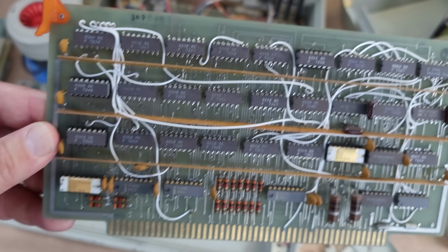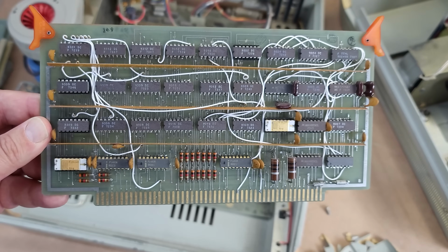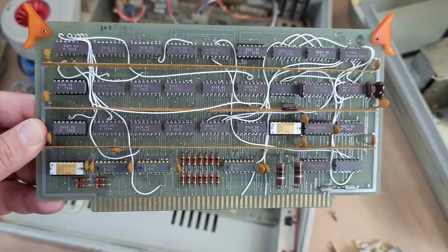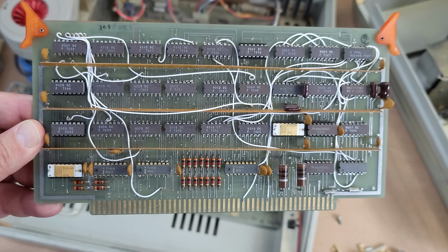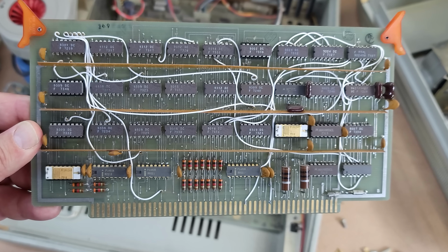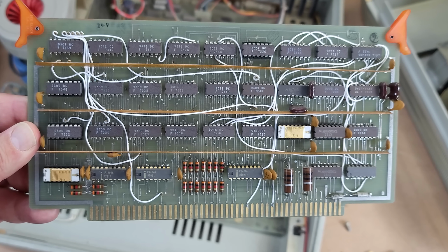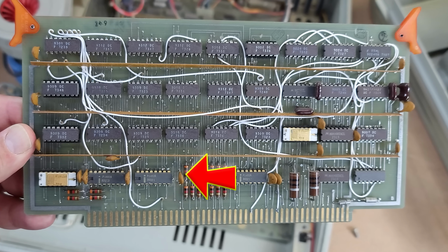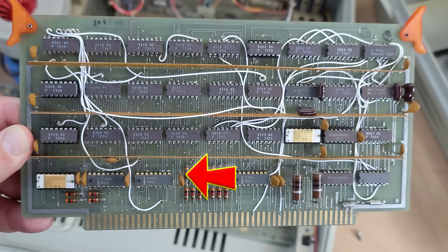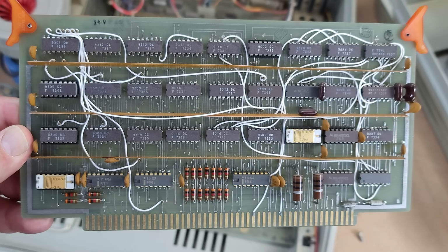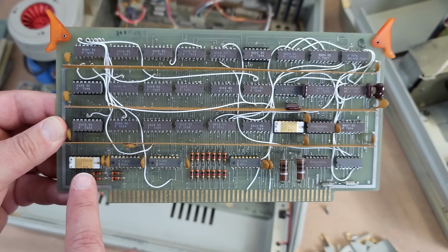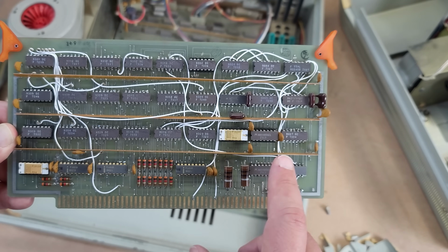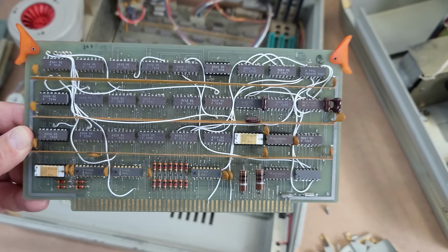Now this board, wow, look at the bodging going on. It's hard to say if this is evidence of a design that wasn't fully dialed in yet, or if they were being produced in a low volume. Early 70s, it could be either. The wires aren't strapped down or super neat, so I don't think this was being mass produced like this. Based on the presence of these Intel 1402 shift register chips, I'm thinking this may have been a memory board. What's interesting is in addition to the plastic encapsulated Intel chips, they also have some Microsystems International second source 1402s in white ceramic. So they're kind of picking from different parts bins here.